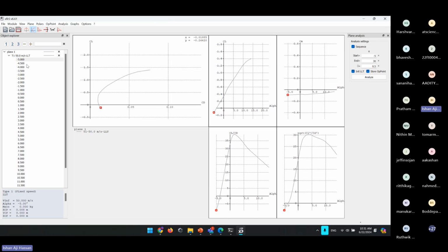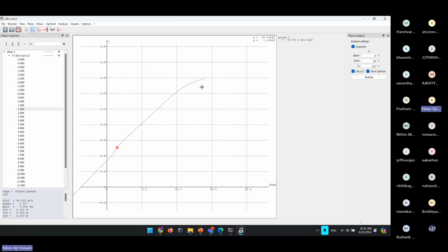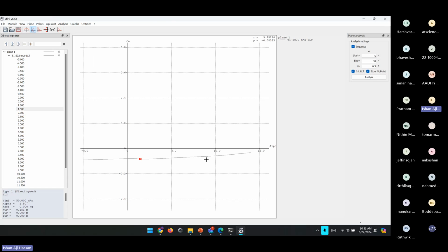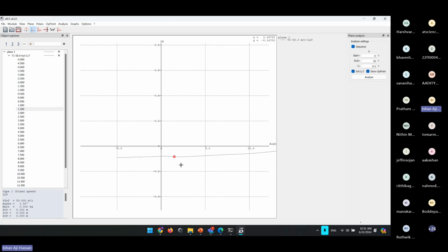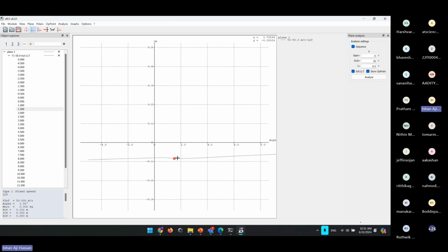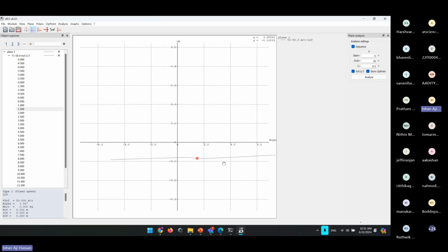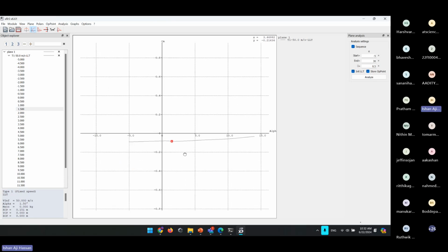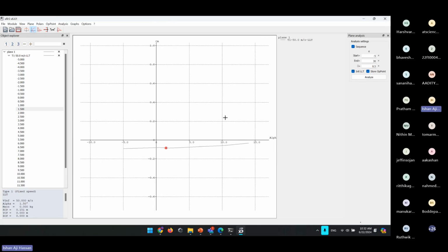So yeah, now you can see the same graphs that we did earlier, CL versus CD, CL versus alpha, almost the same linear trend we're seeing for CL versus alpha. Then CM versus alpha, like we said, we're basically taking it about the aerodynamic center, which we found by trial and error. And that is why it's almost a constant with alpha. It is still changing at a higher angle. So yeah, that is your CM versus alpha.